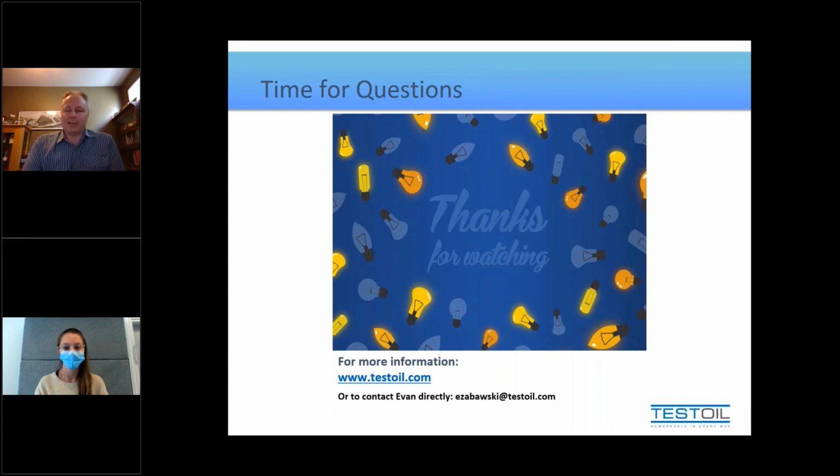So if you have a target like, say, NAS 7, and you get the results back from the lab and it's NAS 8, and therefore you know it's a fail, what you really want to dig into is which range failed. Was it the 5 to 15? Because that could be really tricky, trying to get the oil clean enough to meet that target. Or was it the greater than 100, which means maybe it took just one single particle at that range to end up as a class 8, and you can easily clean it up and get it into range. So I like to see NAS results reported with all the classes for each range, just so I have an idea exactly why the particle count is or is not meeting the spec, versus the single code way, which, like I said, doesn't give you the proper guidance.